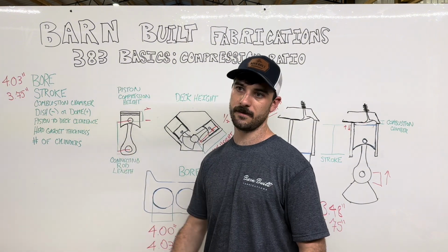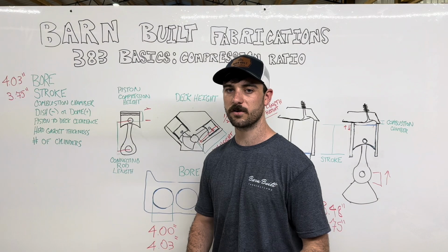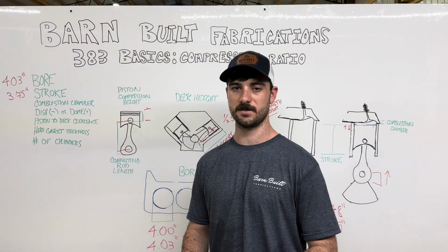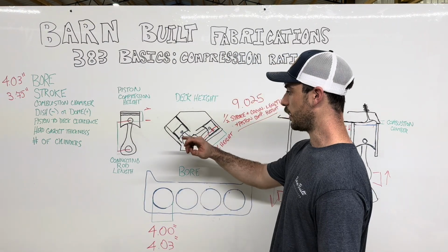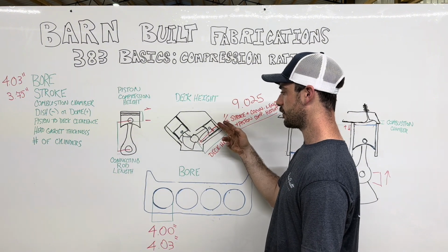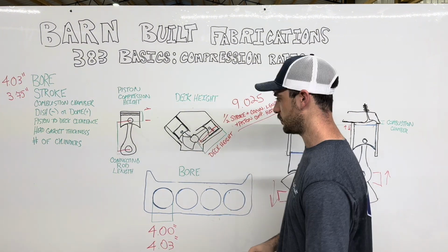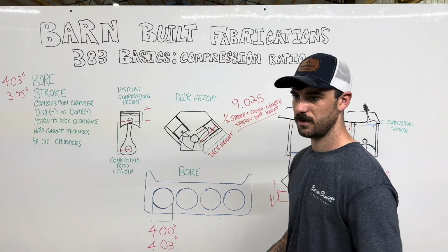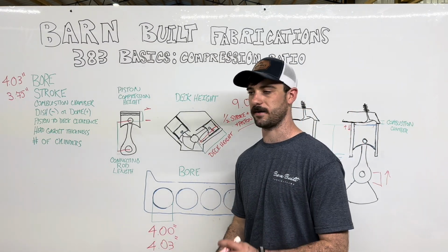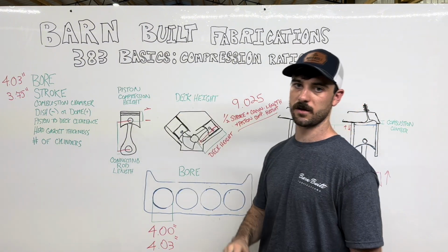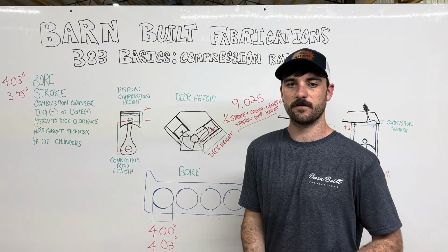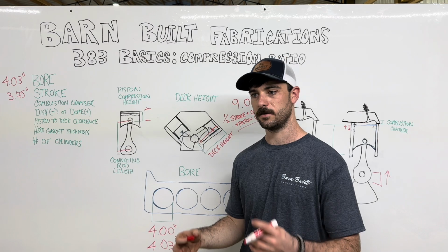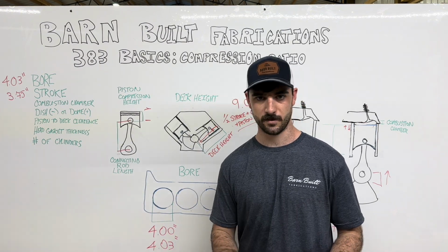So I was able, so far with what I'm looking at, to figure a lot of these things out. And again, not to throw you guys off and confuse you further, which I probably am on a pretty good trend of, there are also taller compression height pistons that different manufacturers make, to accomplish a tighter clearance to raise your compression ratio. It's called your squish or your quench, without having to cut the deck. Cutting the deck is milling down the surface of the block to bring that down. So there's a few different ways that you can accomplish essentially the same end goal of adjusting the squish or the quench, or your compression ratio, etc.